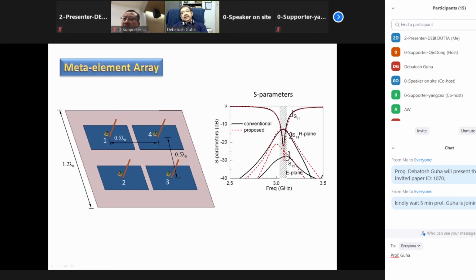There is no change in resonance. There is no change in the mutual coupling between 1 and 4, that is the H-plane coupling. Interestingly, there is a considerable difference in the coupling parameters in E-plane. That means the poles carrying current are mutually interacting. So this is one engineering issue that has to be resolved. The problem is open to all.